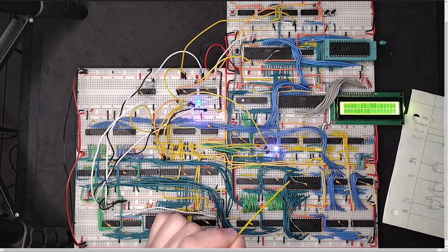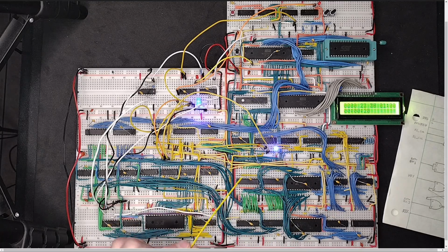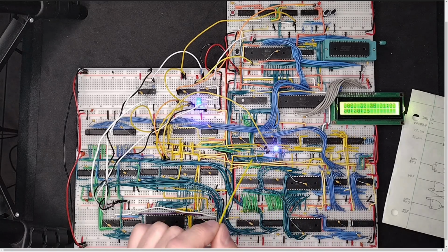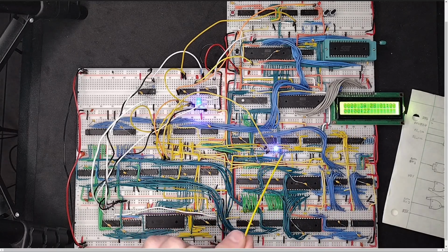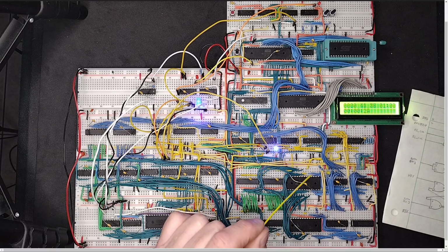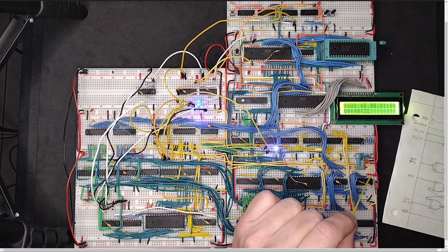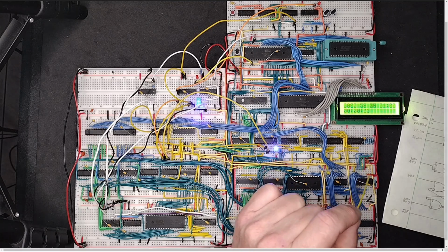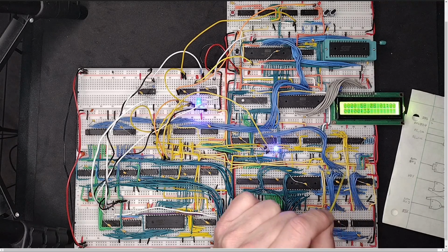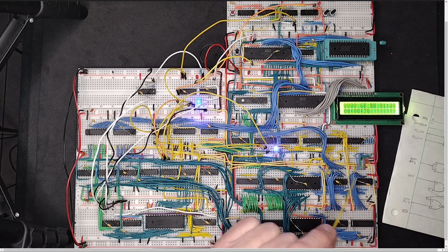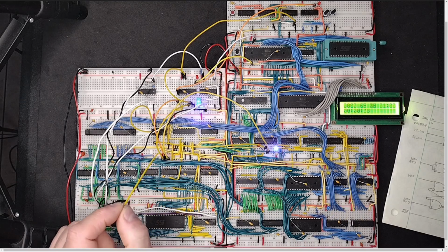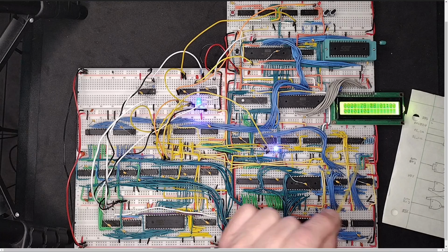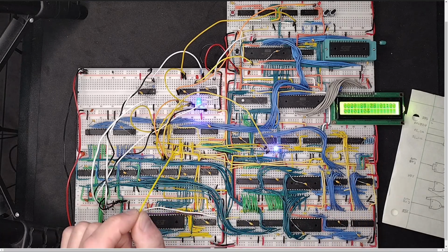So I had to rewrite the software a little bit in how it generates the memory test. First of all, before I even begin the test, I write all zeros everywhere in the memory. Then when I'm testing the foreground memory only, I'm simply masking out bit 6, so it cannot write a 1 to bit 6. It can only write a 0 to bit 6. Otherwise, the test values work the same. That way, I'm never actually triggering this. So technically, I haven't really tested this part yet, but I'll get to that when the time is ripe.